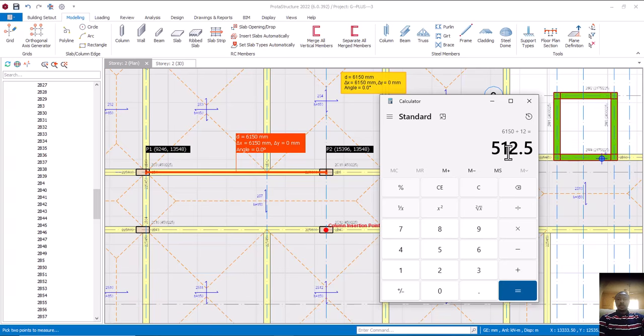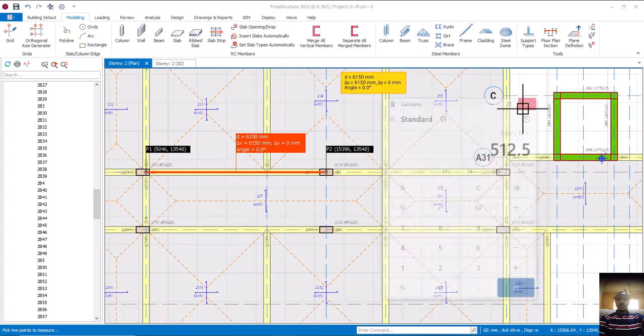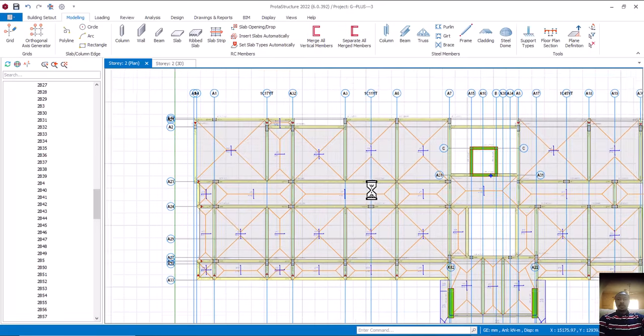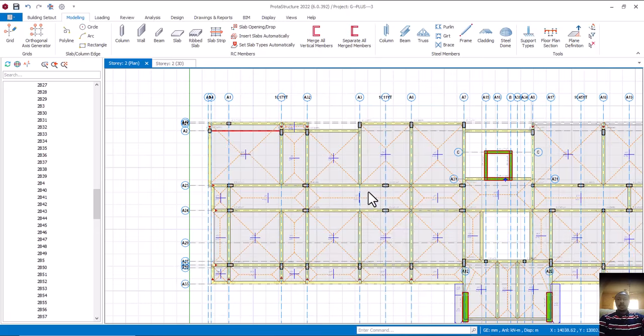Approximately 600 is still okay. So 450 can still go, but because of this secondary beam that's going to act on this one at more load, that's where we are going to be putting 600. Which definitely you should pass the design. That's how you get your beam depth when you're having a long span of beam.